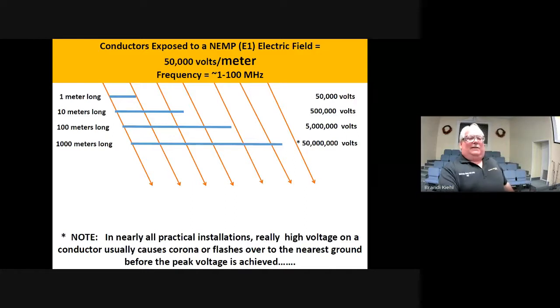Now, back down here on Earth, if you have an EMP go off, a typical one is around 50,000 volts per meter field strength, which means if that pulse goes by a 1 meter long wire, that wire will have 50,000 volts superimposed on top of it. If you have one that's 1,000 meters long, you're talking 50 million volts. Okay, this is serious business here.